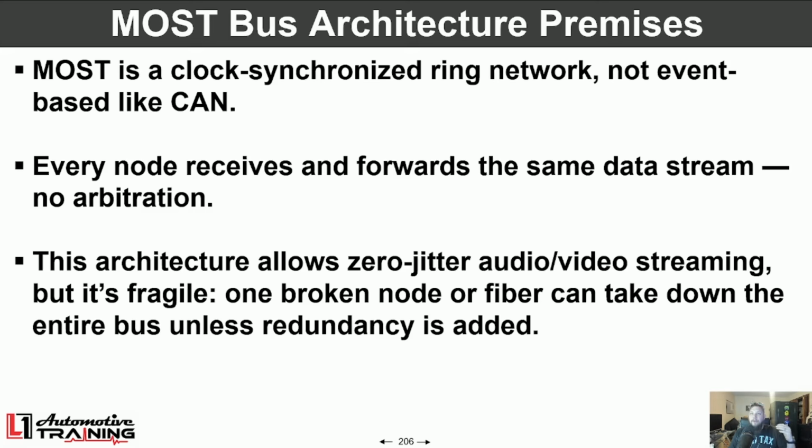So it's really just a lot of isolation of one circuit to another to determine, okay, is this a module or is it on the physical layer of the network? And if it's physical layer and it's POF, whole entire harnesses have to be replaced. And it's similar with UTP style and coax. You're going to have to replace. They don't have very many repair options for those, but you'll see that's what you'll find.